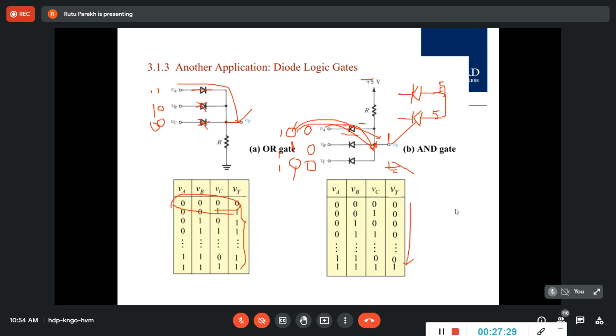Okay, and with the same diode here, I'm giving one time 0 volt, and here I'm giving 2 volt. Then which is more strongly biased? The one with 0 volt. The one with the larger difference, right? So that is more strongly biased. So if it is 1 here and 3 here, this is more strongly biased than this. The difference of the voltage, you see, right? That was on the same ground as what we had done before.